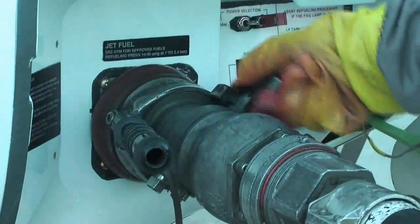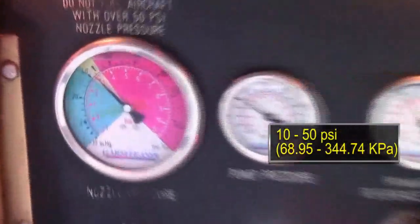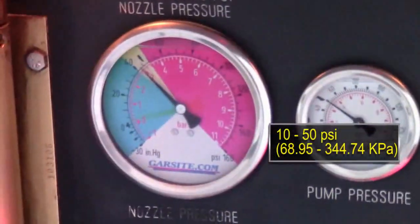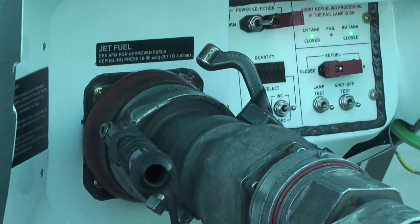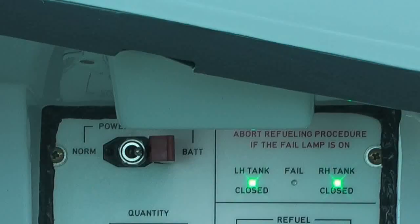Open the valve handle on the fuel nozzle. Pressurize the fuel system from 10 to 50 psig. Make sure that the left tank and the right tank indicator lights are on and there is no fuel flow. Make sure the fail indicator light is off. If the fail indicator light is on, stop the refueling procedure immediately.